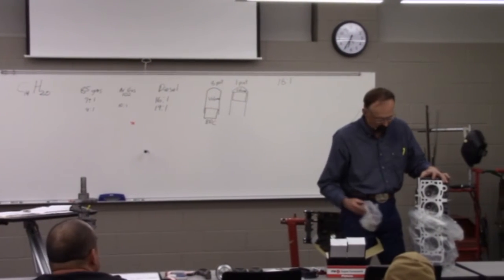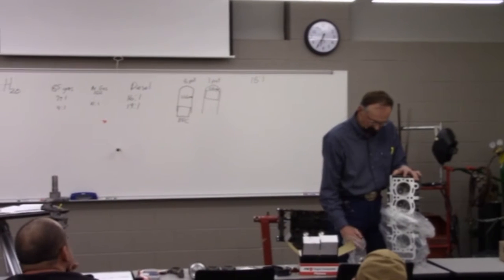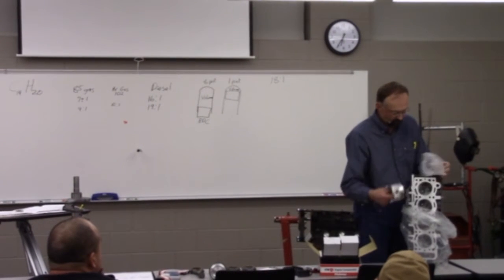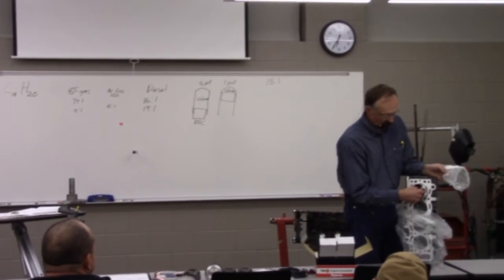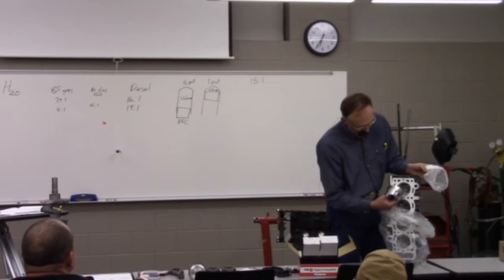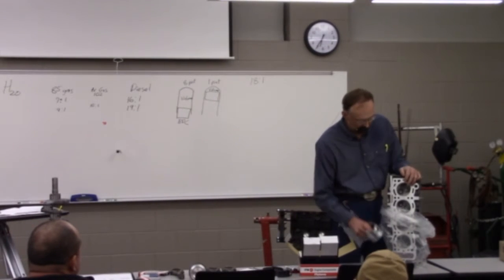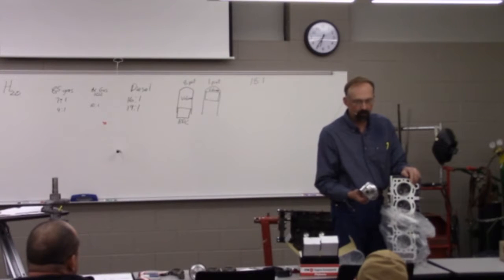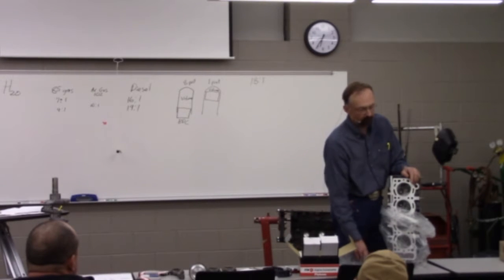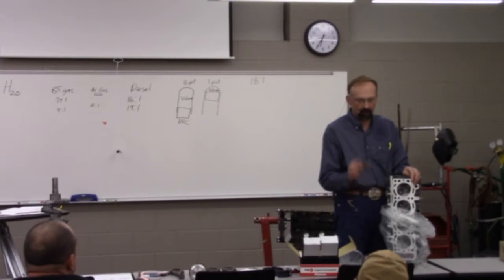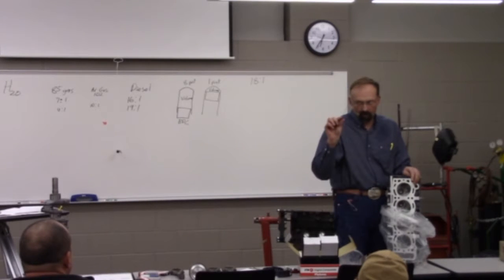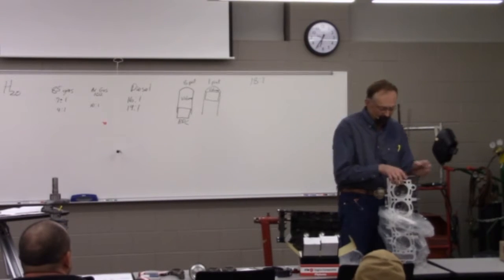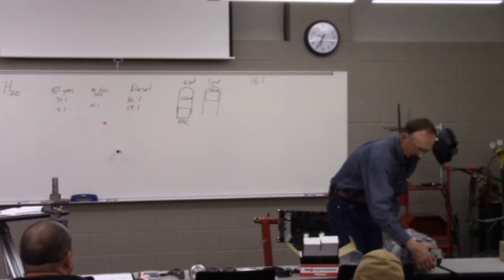And it's between that and the top of this piston is where we're having that combustion. Well, you can see there's a pretty decent area in this engine, but in that one out there, if you noticed, it's a fairly flat top piston and it's a fairly flat head, and they come where they're just all but kissing each other. There's just not much space left in there.